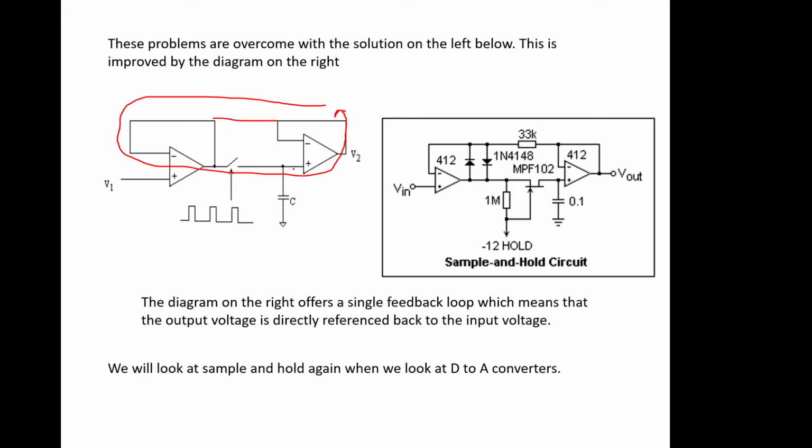And then when you close the switch, there's going to be a disjoint between the voltages, and there's going to be a big surge, because normally this will have gone to one rail or the other. So these designers put a couple of diodes in here to limit the amount of movement, so that when this is open, this voltage can only move by a maximum of 0.7 of a volt in either direction. So it's been clamped. And then when you close the switch again, this output, instead of going to one rail or the other, has only gone to about 0.7 of a volt, so it hasn't got to cover as much ground to recharge this switch up.